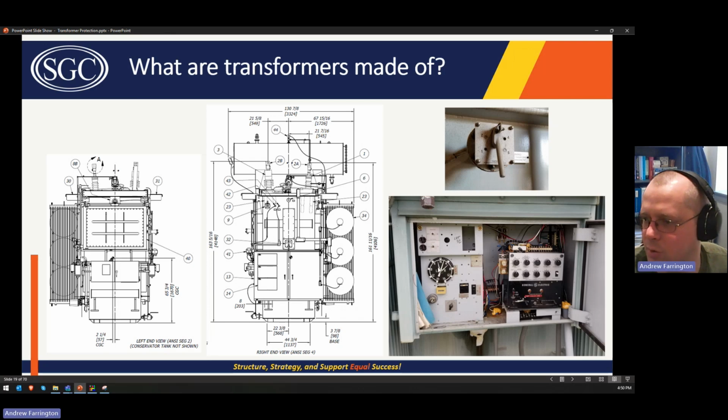And so let's say we hit the button that resets the drag hands. I think it's probably this thing here. This resets the drag hands. So there's a spring that returns both of these to the current LTC position. There's a little pin on each of them that when the LTC position changes, it pushes on that pin, and the drag hand moves with it.